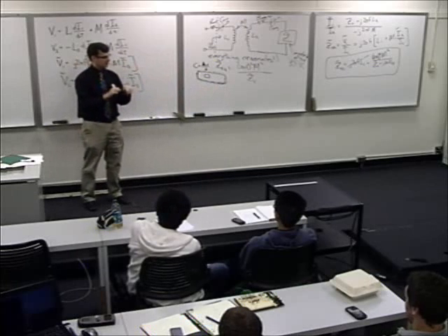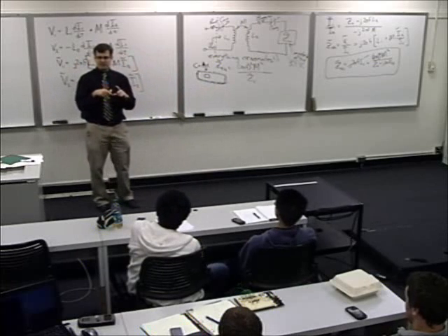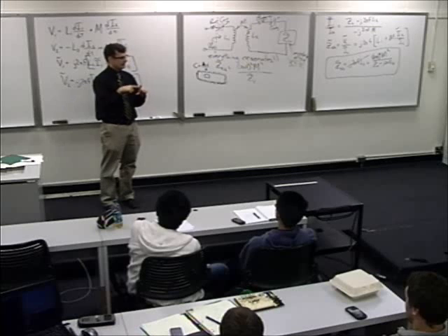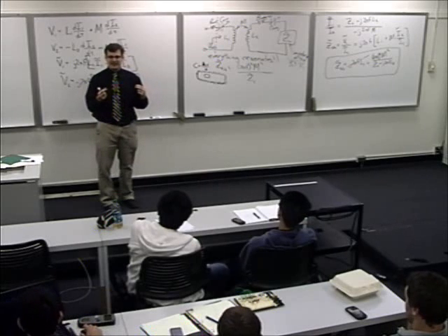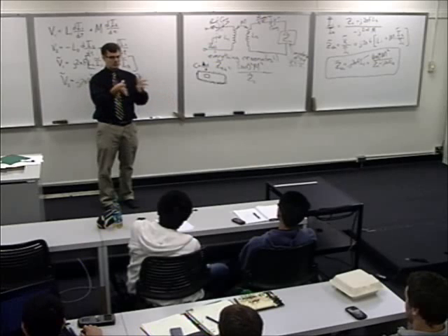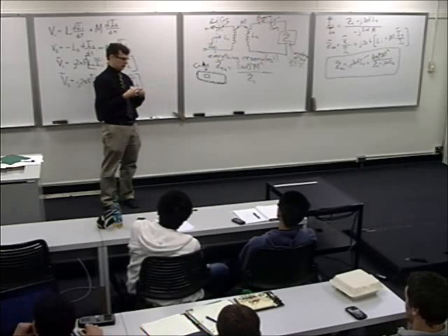However, there are some tricks. One, you could put some magnetic material inside the coil. That is usually a polymer with ground up iron components in it. Almost like, at that point, you're trying to make it look a little like a cruddy transformer. The magnetic material will conduct a little more magnetic flux, and you might get a little bit of range out of it.